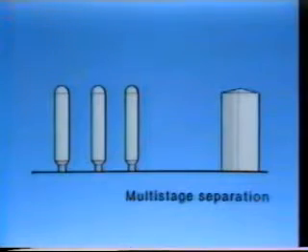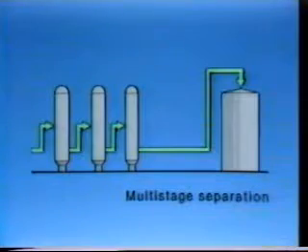This means that a long series of separators, each operating at a slightly lower pressure and allowing for the removal of the liberated gas from each stage, will allow for the highest oil recovery in the storage tank. This type of continuous separation is not economically feasible. However, multi-stage separation with 2 or 3 separators can approach the optimal yield, and that's what we often see in practice. The oil separated at one stage goes on to the next.